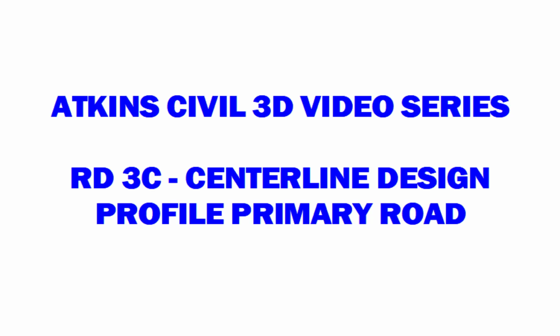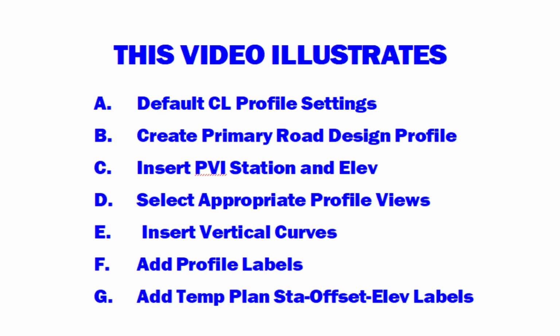Atkins Civil 3D video series, Road 3C, Centerline Design Profile, Primary Road. This video illustrates: A. Default Centerline Profile Settings, B. Create Primary Road Design Profile, C. Insert PVI Station and Elevations, D. Select appropriate profile views, E. Insert vertical curves, F. Add profile labels, and G. Add temporary plan station offset elevation labels.